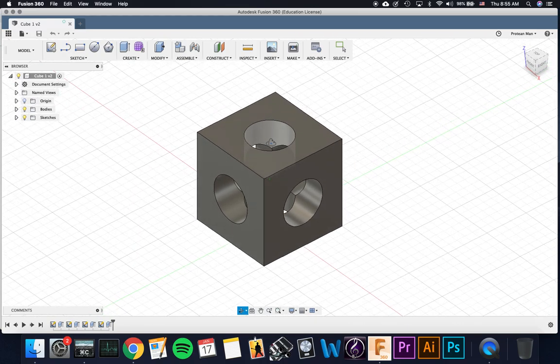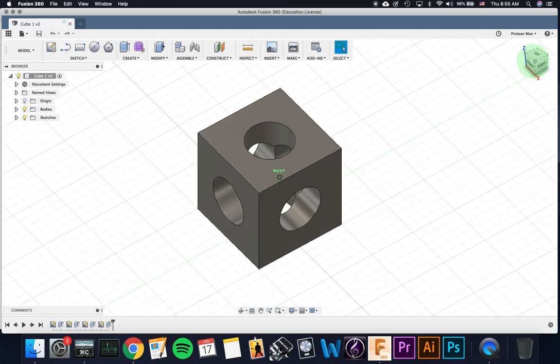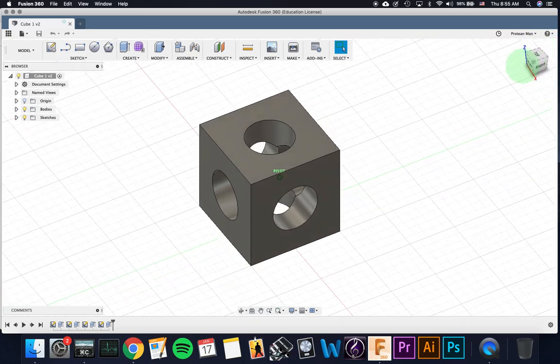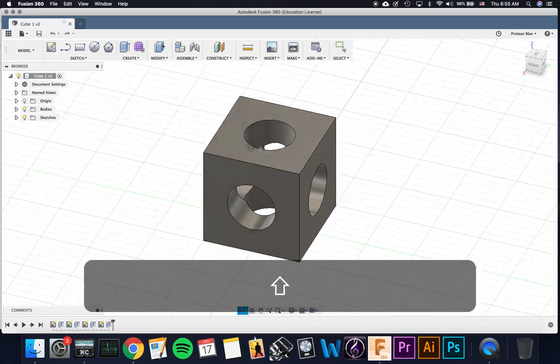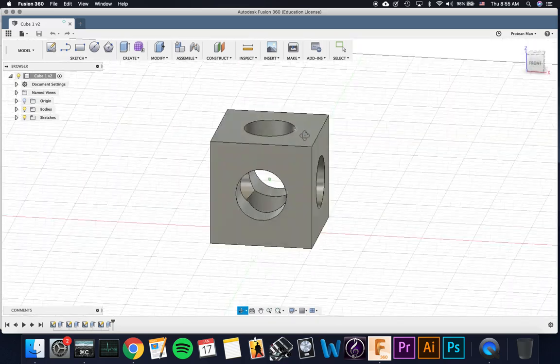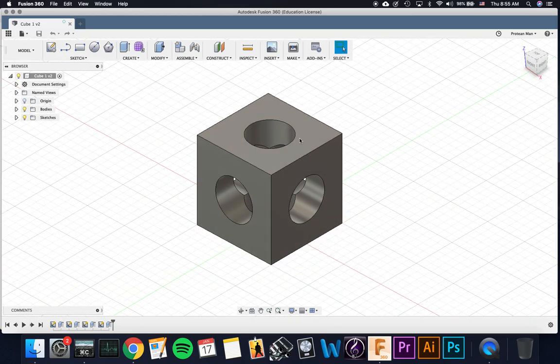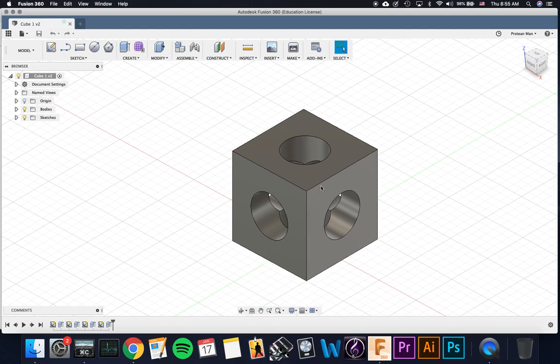Most people by default go back to this when they first begin to rotate. This little rotation box, the camera angle box, shows you the top, front, right, and so on. But I use Shift and the middle mouse button because one, it rotates faster. I can spin everything quite quick, and it's a little more fluid. I don't have to move my entire mouse over to go over that camera box.